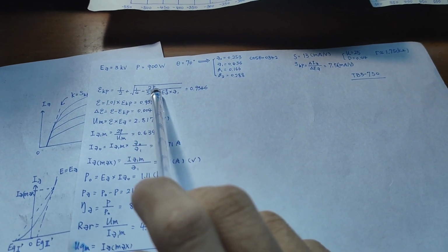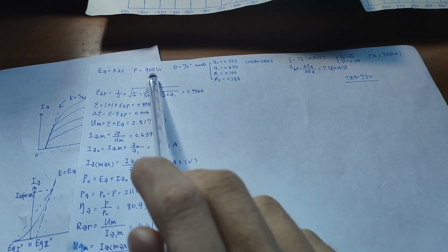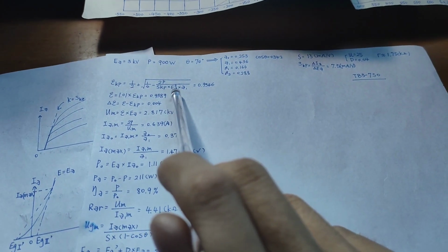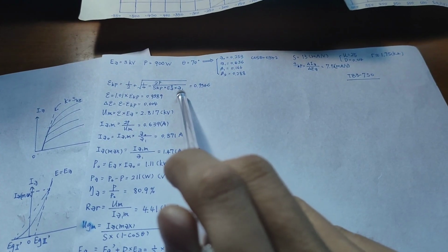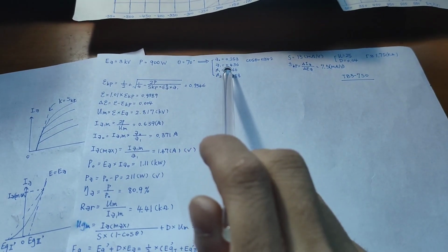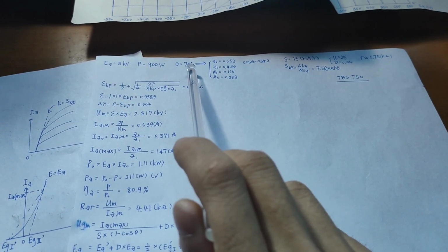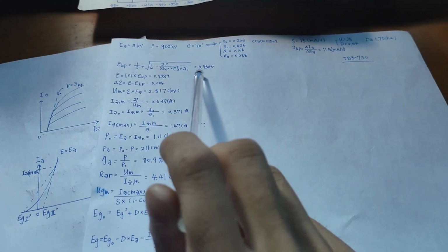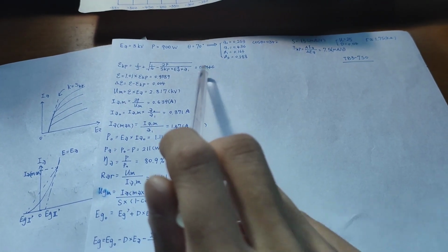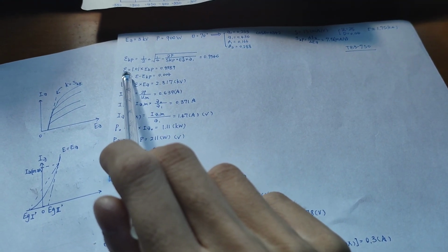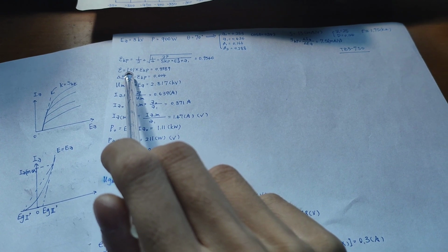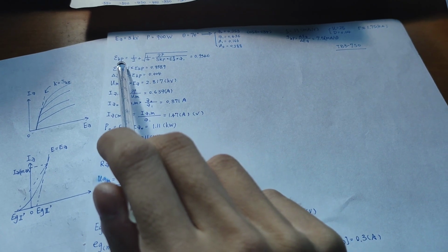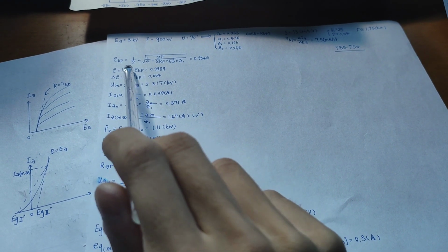You see the designed power, and this constant we just calculated here, your anode voltage, and this constant, which will be 0.436 under the condition of just 70 degrees conducting angle. So you can get this one, and you need to get this coefficient, which is around 1 to 1.02 times this constant. Here I simply use this one.